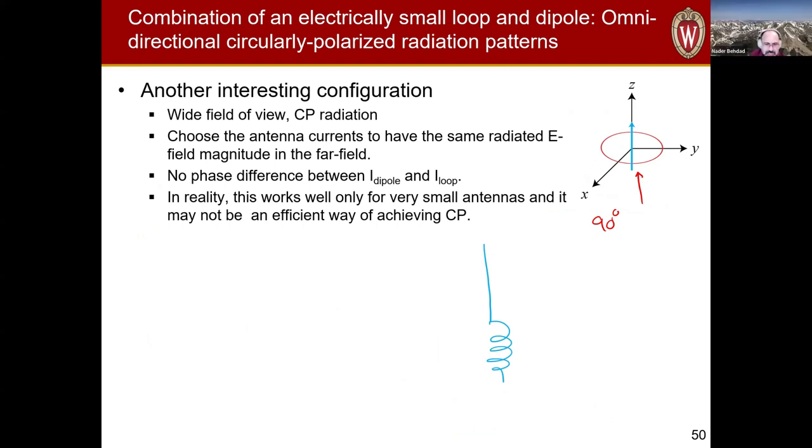Sure, I think you can do it either way because as you mentioned, the coil is really part of the matching network. So what you're doing here is you're basically inductively loading it to make it resonant, or bring it close to resonance. And if the antenna is pretty small, you still need to tune it with an impedance matching network. In the ham radio context, depending on the radio you're using, a lot of these ham radios have automatic impedance tuners in the output stage, but you can also use an external antenna tuner as well.